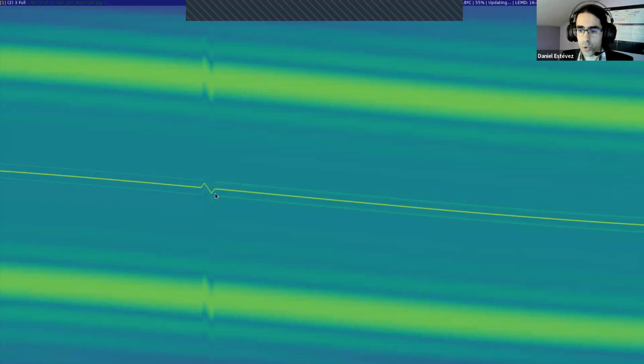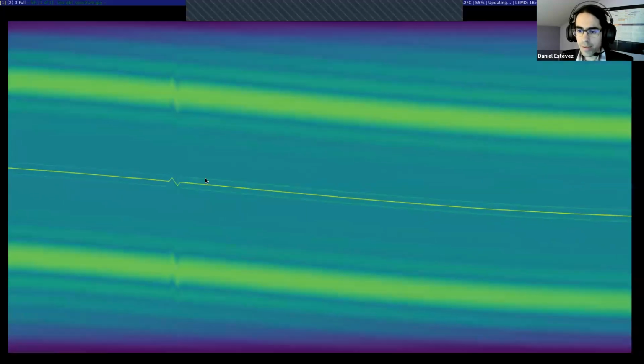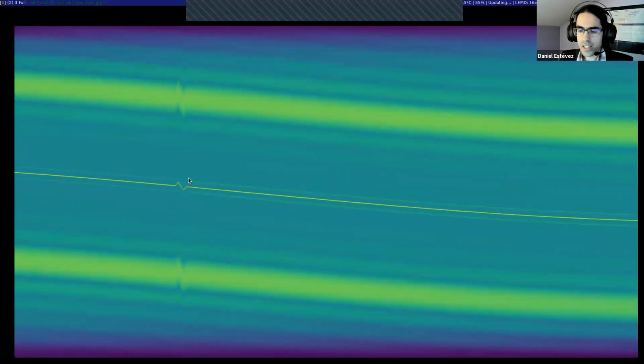And they do this for two reasons. First, to pass in front of the rest frequency of the spacecraft receiver. And the second is to have a very clear visual confirmation that the spacecraft is locked. If the spacecraft follows the sweep they've done, it is locked. If it doesn't follow it, then it's not locked, and they need to figure out what the problem is. I'm giving you lots of detail on this because, just by chance, it more or less matches the beginning of the message transmission, or it seems to be related to the message transmission in some way.